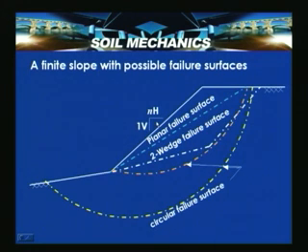For example, if it is an embankment constructed for an approach road, what should be the safe slope? Suppose a cutting is being made, so it has to be pre-designed based on the available properties of the soils and the conditions, whether it is short term or long term. We need to look into what is the safe slope which can be allowed.